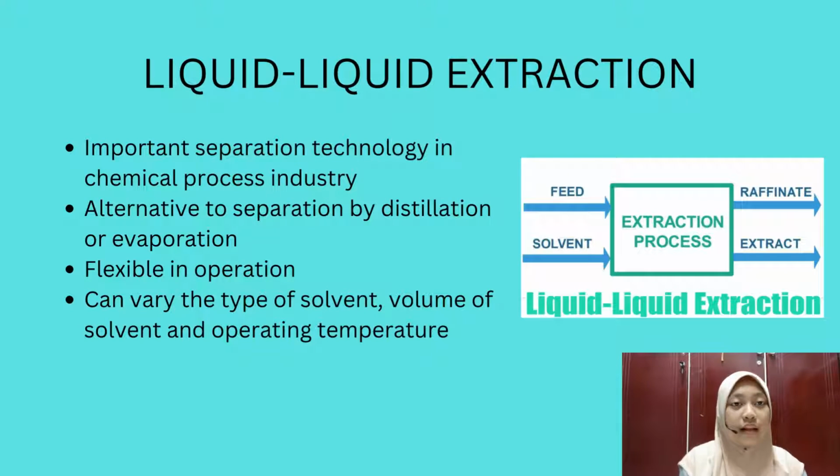LLE, or liquid-liquid extraction process, is an important separation technology for a wide range of applications in chemical process industries, as it can sometimes be used as an alternative to separation by distillation or evaporation. LLE also offers flexibility in operations, where the type of solvent, volume of solvent and operating temperature can be varied.